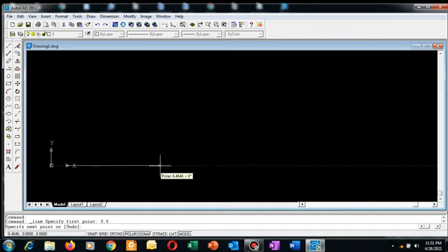So you need to keep displacement on x-axis. How many units are we displacing this way? So we are displacing 10 units, but on y-axis we are remaining the same point, so we are displacing 0 units. So remember, for relative coordinates we start with at. So you say at, you give x displacement, which is 10, then you give now y displacement, which is 0.